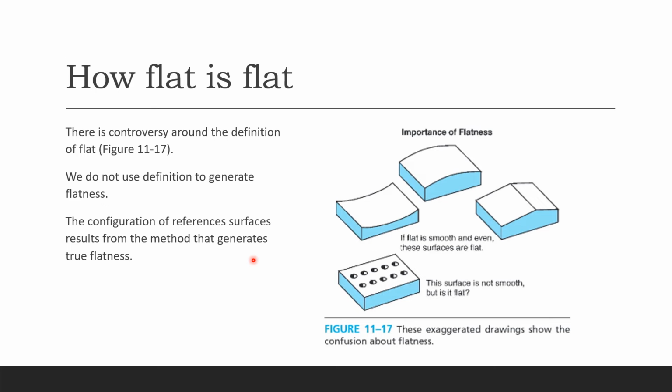How flat is flat? There's controversy around the definition of flat. In this figure, these are just exaggerated drawings again, showing you the confusion about flatness. We do not use the definition to generate flatness, because you can't use it. What we do is, the configuration of your reference surfaces results from the method that generates the true flatness. So you just have to get on and make it.